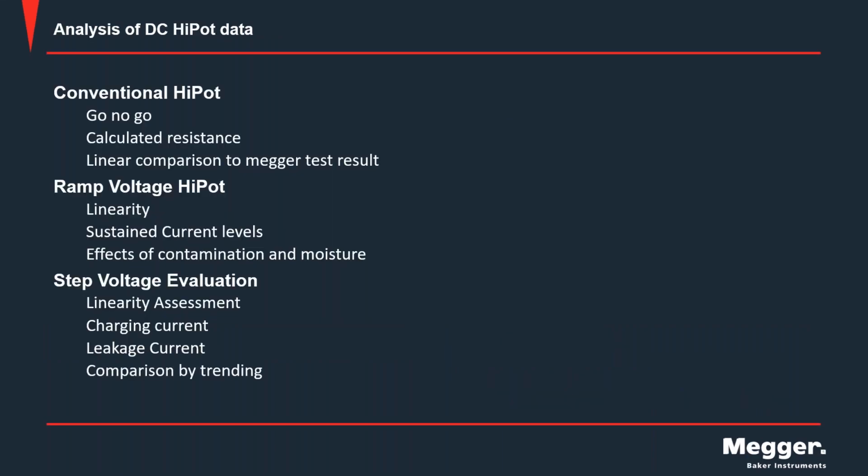So at this point, we've only done low voltage testing. To go to high voltage testing, then would be the high pot for the DC test. We have the conventional where you raise your voltage up to the test potential, wait for that 1 minute, and it's a go, no go kind of a situation. Again, we're going to look at minimum megohm value where the tester's watching the current, making sure that it doesn't increase rapidly or trip or detect an arc.